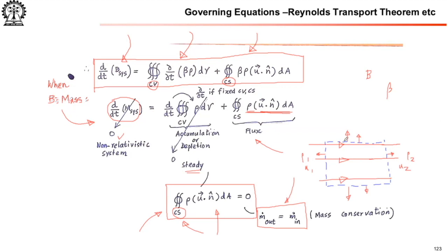So what will happen is, these surfaces will become zero in terms of this number. So if you want to do the control surface integral over this whole control surface, let us label this as A, B, C, D. In this case, surfaces AD and BC will not even participate because u dot n for these will become zero.